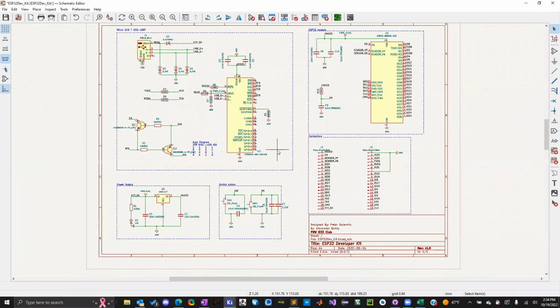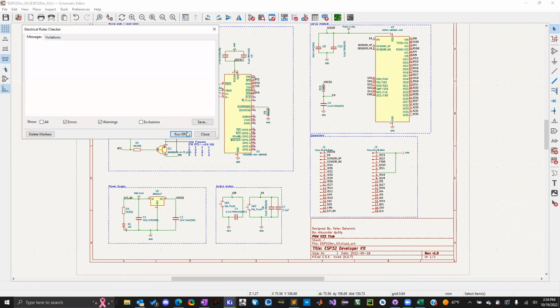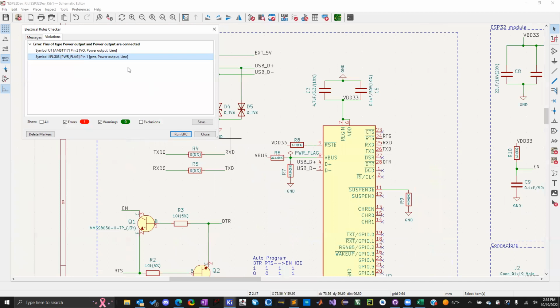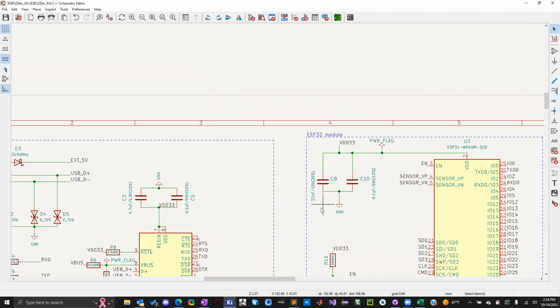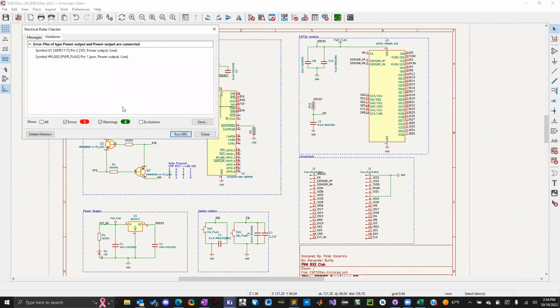So are you guys done with the schematic portion? And you have no errors or anything? Go ahead and run the ERC. I just got this one, which isn't an issue. It's the one that looks like a checklist with the check mark. What kind of errors do you got? This will help you get used to the process.